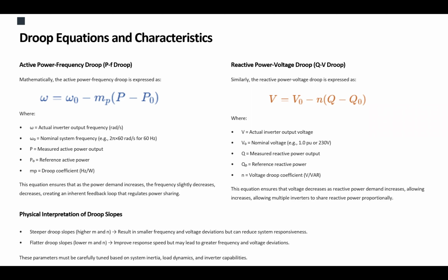Voltage also has a variation margin. That margin is standard, and there is also a standard for how fast you have to respond to the grid. The inverter cannot wait a day to see what's going to happen. There is a time margin. Also, you cannot respond faster than a certain margin, because some transients are not supposed to be addressed.